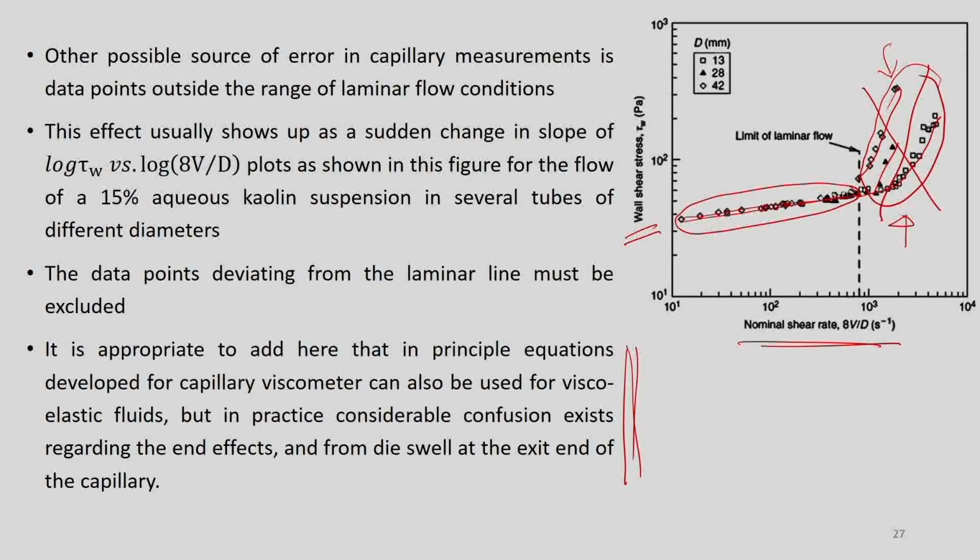Also, in viscoelastic fluids, we know that at the exit point, die swelling exists. We have already seen this in the introduction lectures on viscoelastic fluids. So how to incorporate those effects, all the information is not available. So there is still some ambiguity in using the capillary viscometer for viscoelastic fluids.